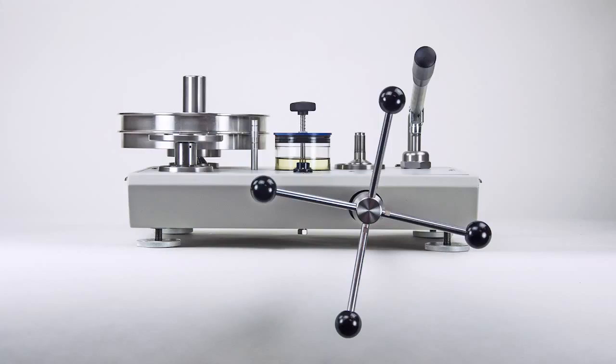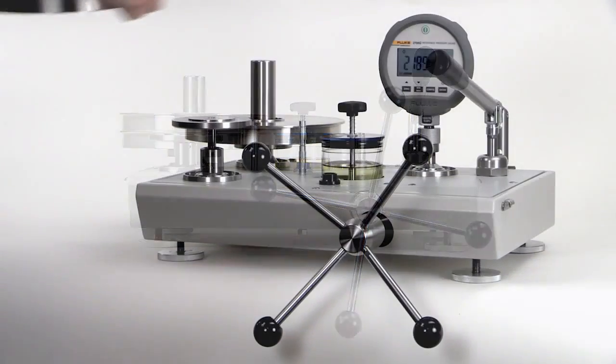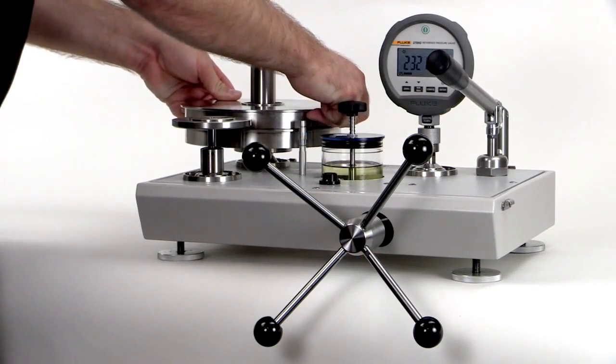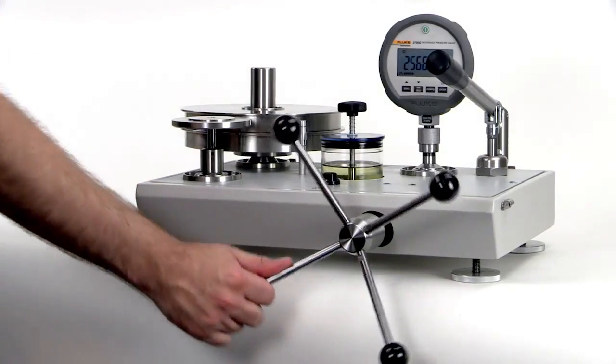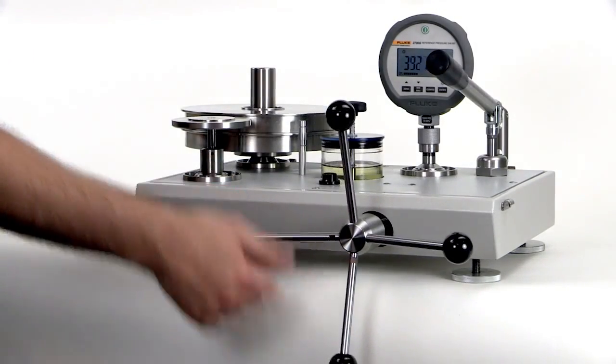This specification can be obtained without performing additional calculations as long as it is used at the gravity specified at time of order, with ambient temperatures between 18 and 28 degrees Celsius, and barometric pressures between 11.6 and 15.2 psi. As a result, no additional software or equipment is necessary. With additional software, it's possible to get 0.008% accuracy with the P3000 deadweight testers. Certain steps were taken in the design and manufacture of these deadweight testers to ensure that this specification can be met without additional calculations by the user.